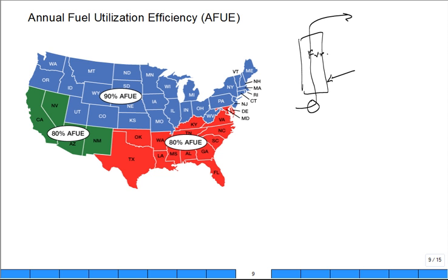It also then, the burning of the natural gas is taken out with a flue, and it goes out the stack, goes out through the roof. You have a pipe that goes up through the roof. What they found is this goes out pretty hot. And what they'd like to do is they'd like to have more of the energy that's in the fuel go into heating your home and less of it go into hot exhaust products leaving your house through the flue.